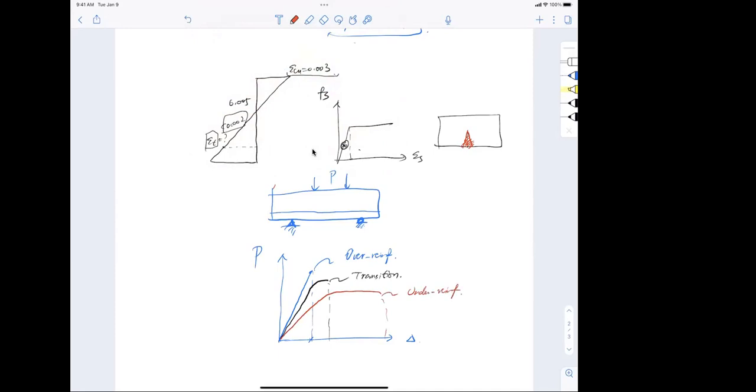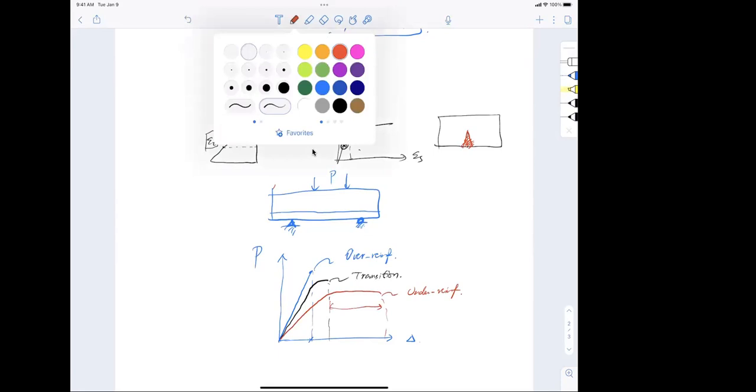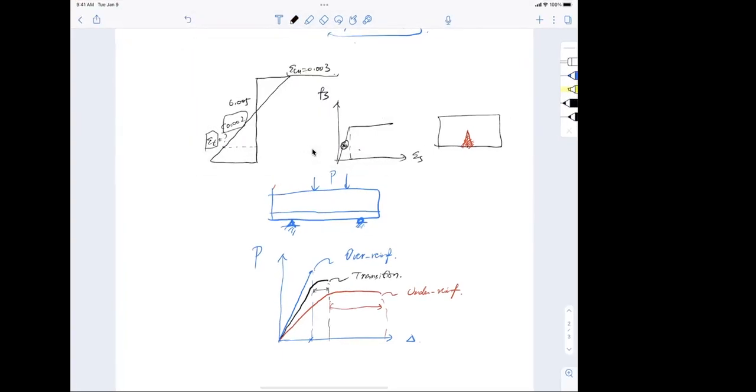Okay, so this period, or this so-called plateau, red is a little bit largest, black a little bit smaller, and for the blue one it's nothing, basically, right? These are so-called ductility. That means when you see the beam start failing, you experience a lot of deformation or deflection already, right? The beam is sagging, basically, and you can visually see it. So you want this, right? Because when you see it's going to sag, the beam becomes like this already, big cracks here, the bar holding it together, you can run.